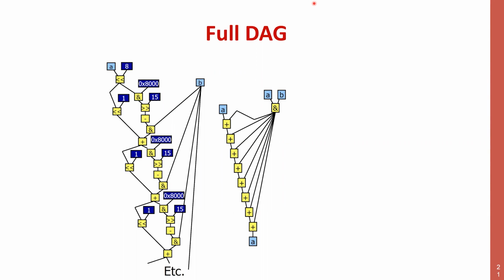So I repeat, or let me compare it with a normal adder. In a normal adder, I have 2 values that enter and 1 value at the end, and the value at the output is the sum of the 2 that enter. Now, this carry save adder has 3 inputs and 2 outputs, but the sum of the 3 inputs and the sum of the 2 outputs is the same.